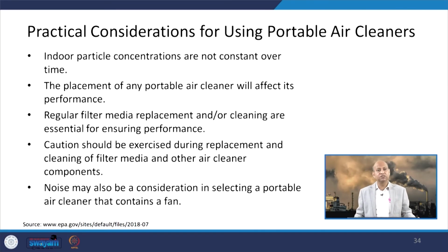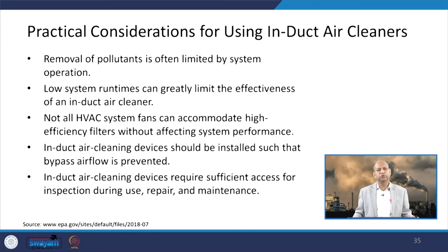Well, then there are practical considerations for portable air cleaners, as I said. Because indoor particle concentrations are not constant over time, the placement of any portable air cleaner will affect its performance. So, we have to be careful where we put it so that efficiency is high. Regular filter media replacement is needed, otherwise it will be a source of pollutant rather than cleaning. Replacement or cleaning of the filter media also needs to be handled carefully, otherwise this will add to the pollution. Noise may also be a concern when we are using some particular portable air cleaners. So, noise pollution may be there, and accordingly we need to ensure that less noisy portable air cleaners are used.